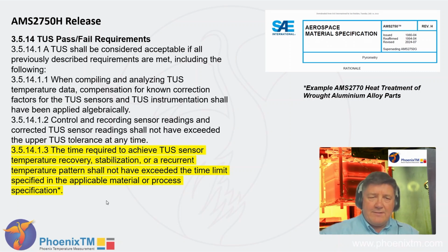As it states here, a key requirement of the AMS2750 is the provision of evidence that the time required to achieve TUS sensor temperature recovery, stabilization, or a recurrent temperature pattern shall not have exceeded the time limits specified in the applicable material or process specification. This isn't actually quantified in the AMS2750 standard itself, but other standards will have this requirement listed. A good example of that is